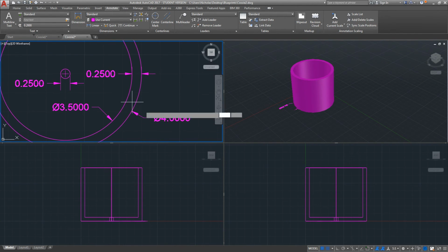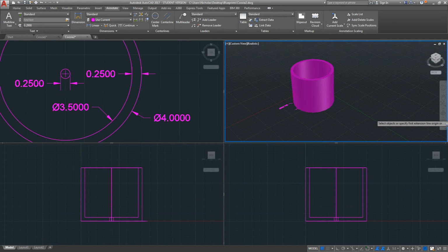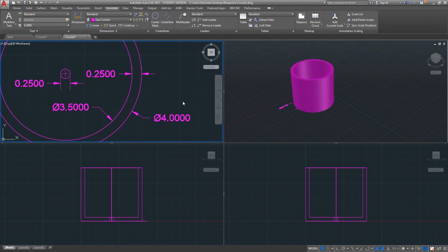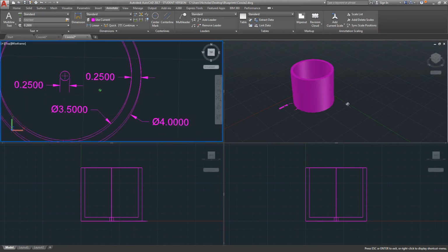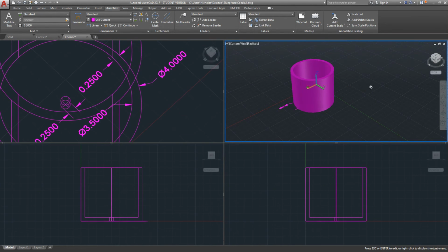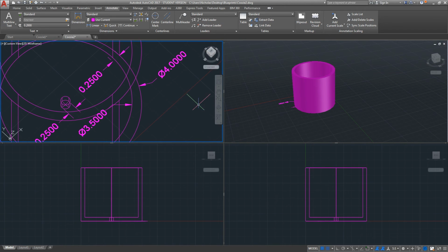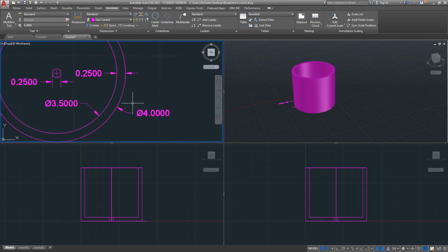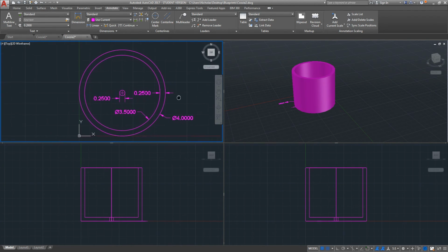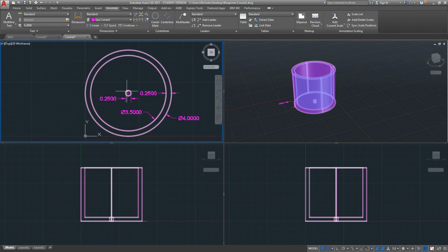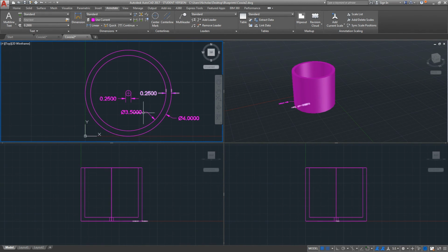There's a rule. You don't cross drawing lines or other dimension lines. That's one of the rules about modeling. So, see what I did wrong here? We got a problem now. Oh, I can't read them. Typically, you're not supposed to model in isometric anyway. Or you're not supposed to dimension in isometric. That's why you have 4 views. You got hole width on the bottom, you got width of the wall on the bottom, you got 2 things.